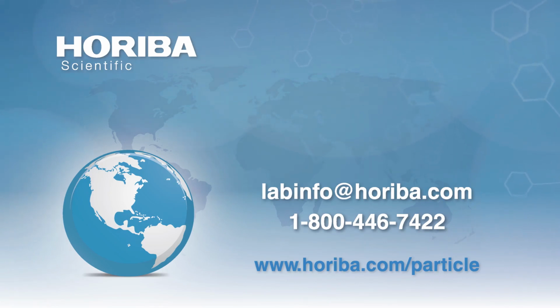What's the answer, Chris? Yeah, 2 to 4 microns, plus or minus 1 to 2 microns, but that is taking our time to produce that measurement over approximately 1 to 2 minutes of measurement in a small bowl system, much like the GPCG2 from the case study that we talked about today. So as good as plus or minus 1 to 2 microns, but your mileage may vary depending on material types